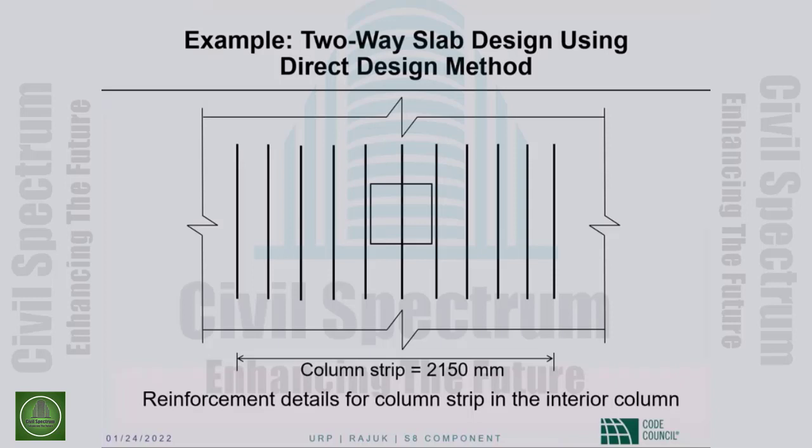Okay. So, is it possible to design flat plate or slab on steel columns? Are there any design considerations specific to that? There actually is. It is called lift slab construction, and that requires shear heads.